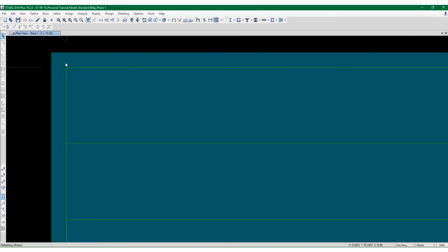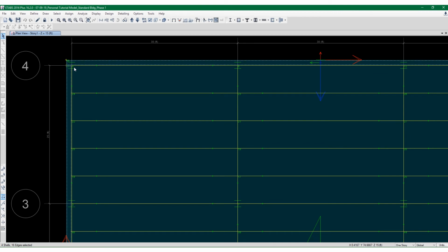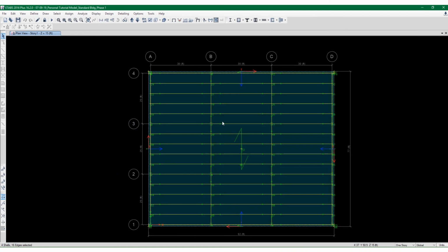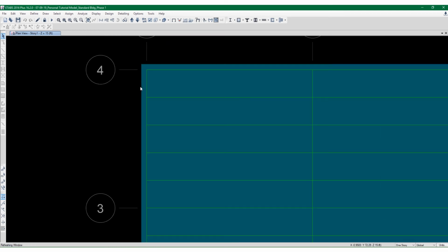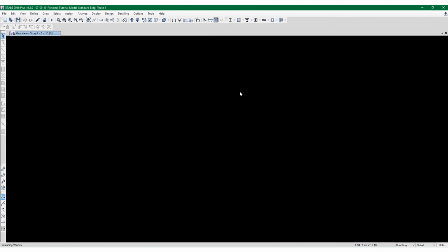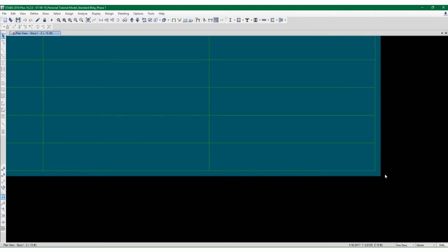And most certainly, if this was a floor, that additional weight wouldn't make it an issue at all because it's highly unlikely that you're going to have that type of uniform load along the edges as well as the interior. People gather in the interior space. That's where the load is. Everything else is really fictitious as far as spreading that uniform load over the entire area. What is the worst case scenario as far as gravity loading is concerned? Get your maximum loads. So that's why it's done.